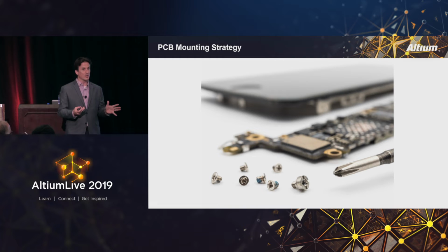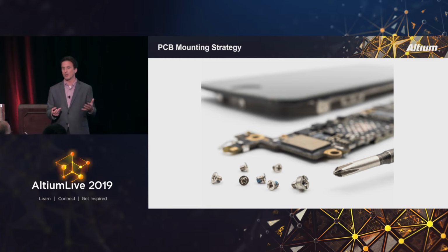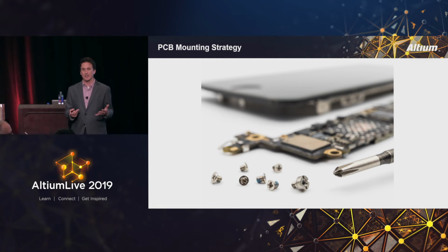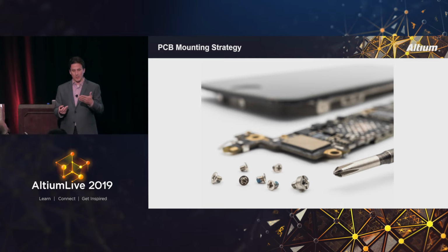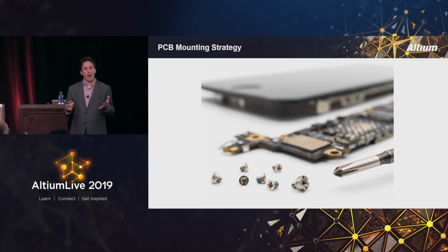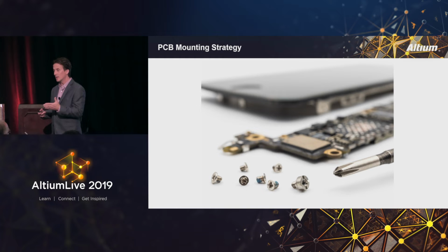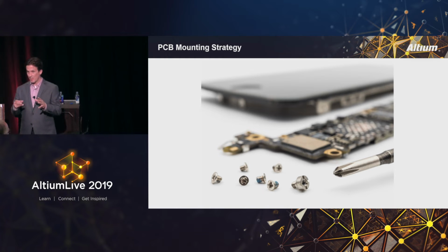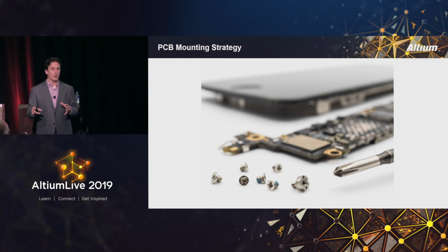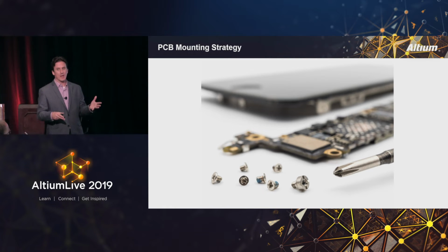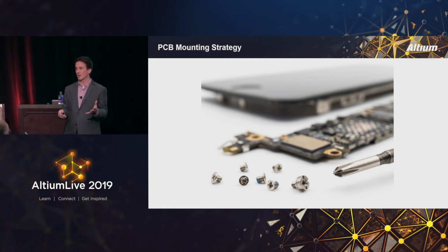Another really important thing to consider in how you mount a circuit board is, if you're mounting this in a metal enclosure, are you grounding every single one of those mounting holes? Are you doing a hybrid connection where you're having capacitive coupling through some of those mounting hole connections and one ground connection adjacent to your primary power entry? You need to have those things figured out before you start laying out a printed circuit board.